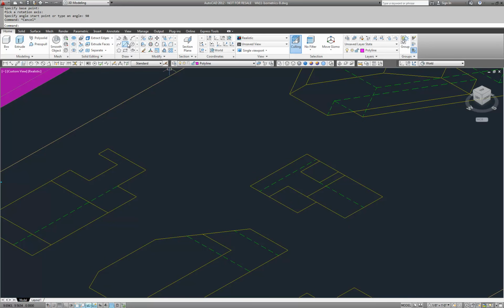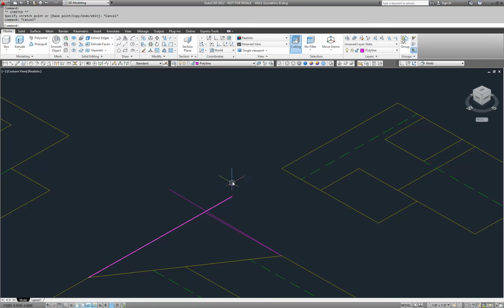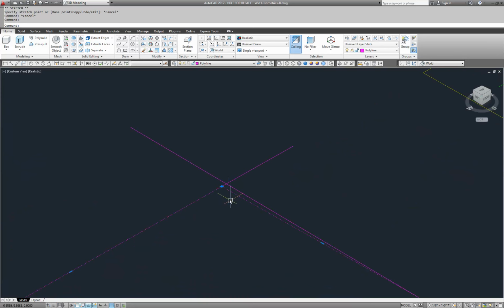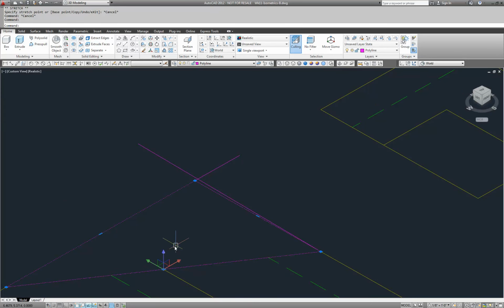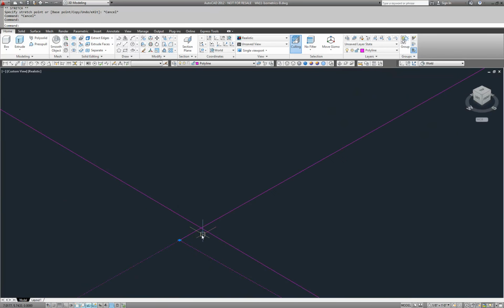So again, I'm going to just draw a couple little helpful lines here, just to make sure you're in ortho, going from that point to that point. And then I'm going to do my polyline. Okay. Escape, and I'll throw these two away. Look, I made a mistake. Now, that's great that I made a mistake. I didn't catch that corner right there.